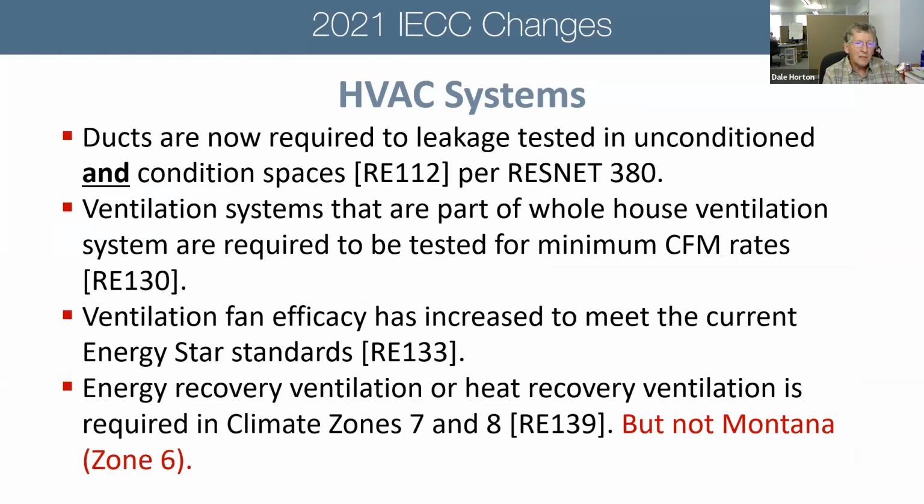Interestingly enough, in the HVAC section, ducts are actually required to be tested regardless of whether they're inside conditioned space or not. And it requires that ventilation systems that are part of the whole house mechanical ventilation system now would have to be tested. So in the 2018, you don't have to test, for example, a heat recovery ventilator ducting system, but you would in the 2021. The efficacy of ventilation fans in the whole house ventilation system would be increased a little bit in the 2021 from the table that was in the 2018.